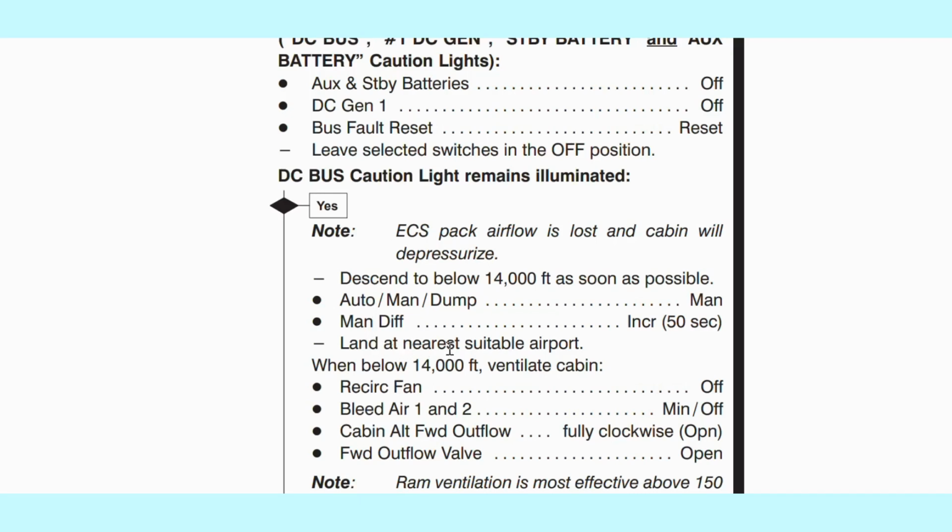Now can you see this one here? If you remember from my earlier videos on the QRH, we actually emphasized these phrases which are in the beginning of the QRH. Here it means that you may continue the flight, okay, or divert or return back depending on your assessment of the situation. Okay, at 14,000 feet or 13,000 feet, the aircraft can still fly, terrain not being a factor, obviously. You can fly, and then you can decide whether you'll continue, divert, or come back to destination depending on how far you are. Okay, it's all up to the crew's discretion.